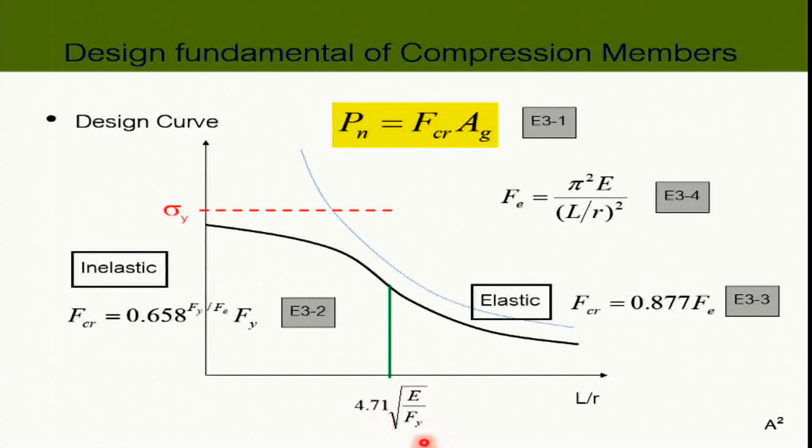Okay, and if you use the SS 400 or SM 400 steel, Fy is 2,500 kilogram per square centimeter. This limit is about, I think, 132. Okay, it's a basic number. If you use SM 520, it's going to be down dramatically, because the stronger the material you have, the lower the buckling limit you're going to have, because when you have a stronger material, it can take more.